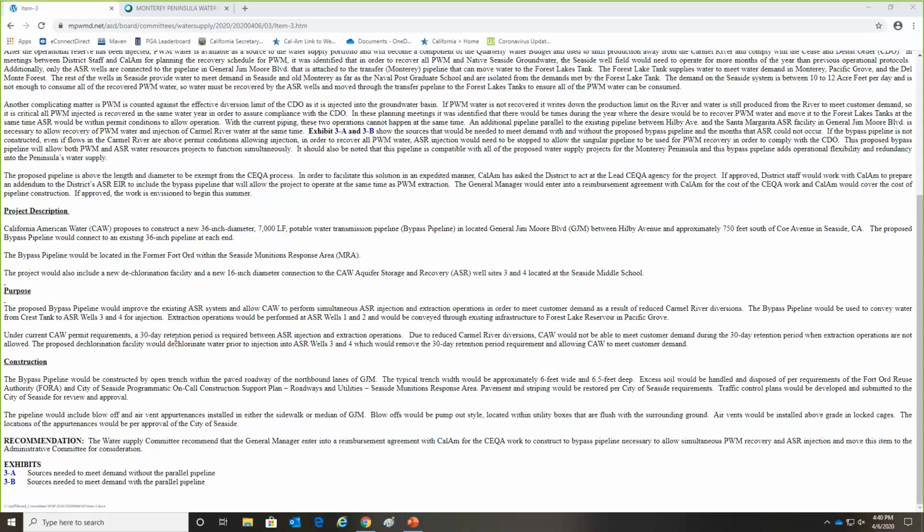So without some type of dechlorination before injecting the water, you must know in your water supply planning that there will be a gap of a month to 6 weeks after the injection season ends that you do not have that source available, due to concentrations of disinfection byproducts.